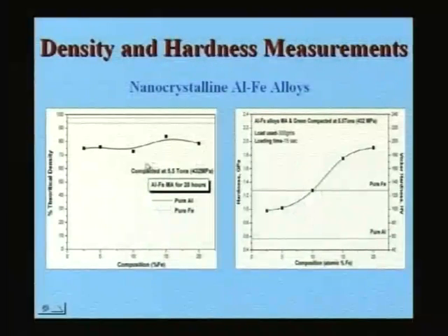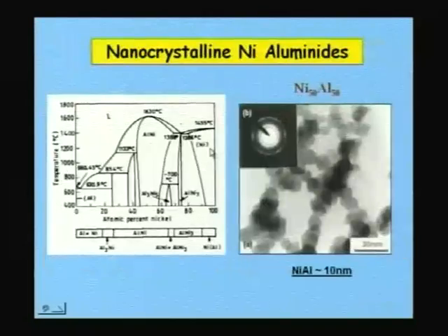Whereas a nanocrystalline material can flow more easily, and you have large grain boundaries available for achieving high densities. That's why, even at normal green compaction, you can achieve almost 85%. In a number of composites, people have achieved even 90-95% just by green compaction. So one can achieve high densities in these materials.